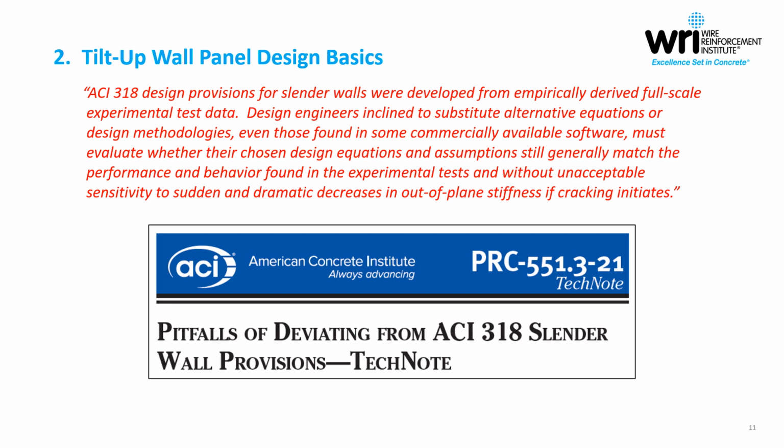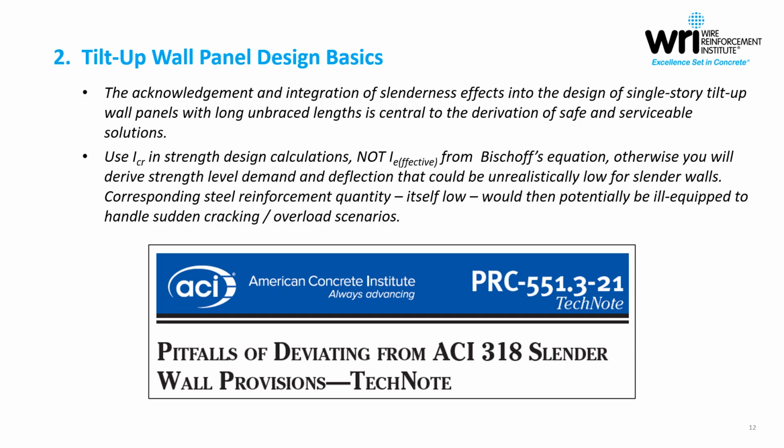So what does this all mean? It means that properly capturing slenderness effects in the design of wall panels with long unbraced lengths is critical in deriving a safe and serviceable solution. It's crucial to utilize cracked section moment of inertia in the design calculations, and we'll see that here in some of the slides coming up.